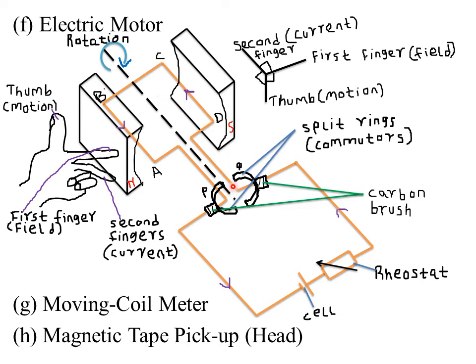Remember, while in that position, our conductors here will be in between the gaps of our split rings. And remember, sides BC and AD are moving parallel to the magnetic field. Therefore, if the sides are moving parallel to the magnetic field, in that case no force will act on that particular conductor. Remember, a maximum force only acts whenever the conductor cuts the magnetic field at right angles or at 90 degrees, as seen by side AB and side DC.